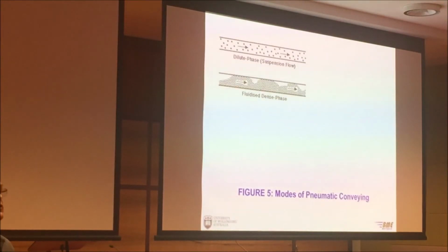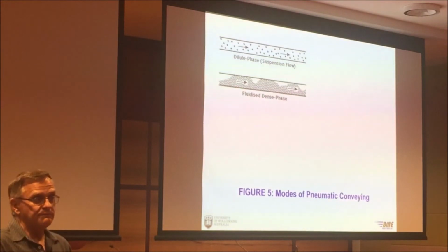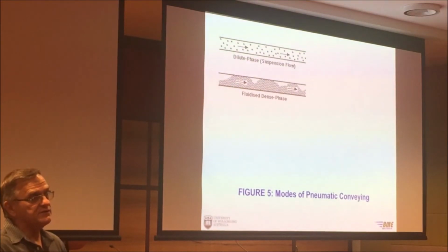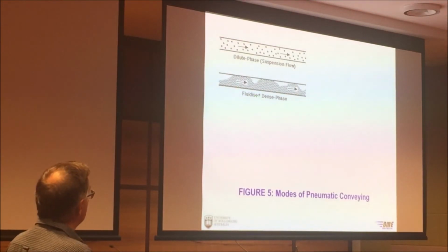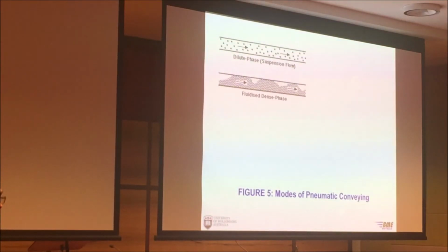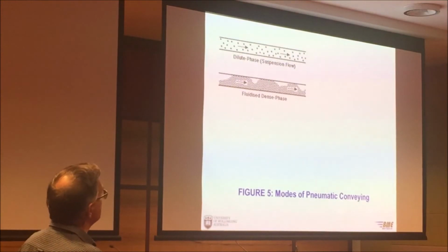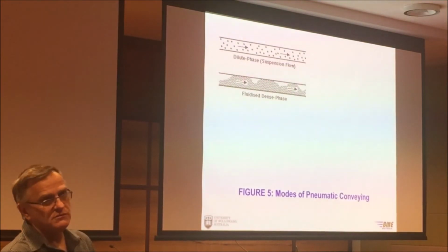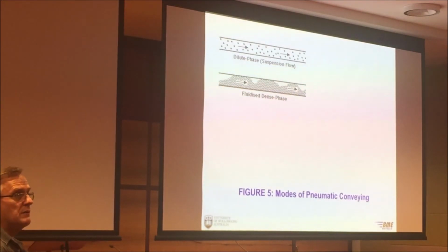And then in more recent times, when I say recent, last 40, 50 years, people developed fluidized dense phase conveying for powders such as cement, fly ash, pulverized coal. So we can, even through a 100 mm pipe, do 100 tons per hour of these types of materials. So it's high concentration flow, it's lower velocities, and in terms of transport efficiency, it's much more efficient than this, maybe 10 times more efficient. So you're transporting a lot more product per unit air.